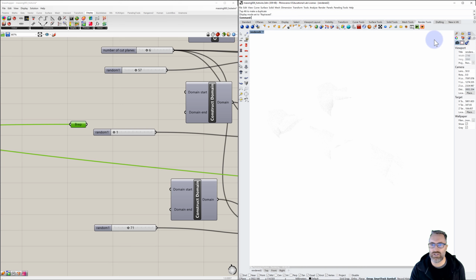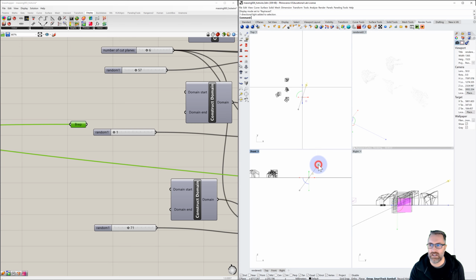So if I come up here to the view, let's see, I need to select the light. And when I do that, we get the properties. So the light's on, the color's white, the shadow intensity, we want full shadow intensity, but maybe let's turn this down to 50 and see what happens. Maybe even 25, and we can render it, and we can check and see how that looks.